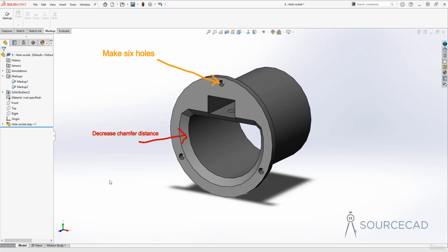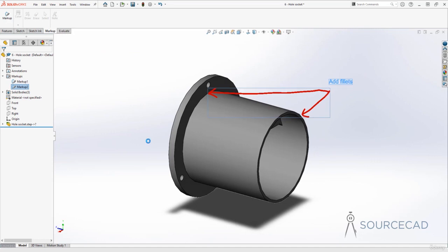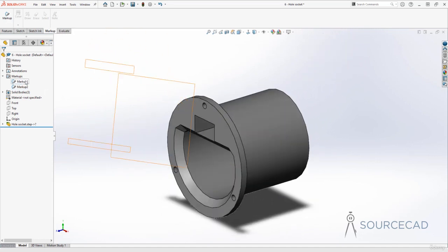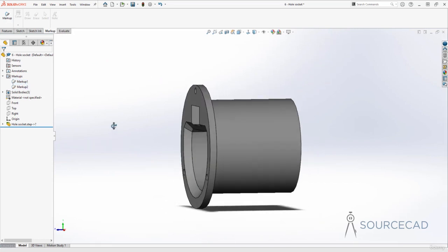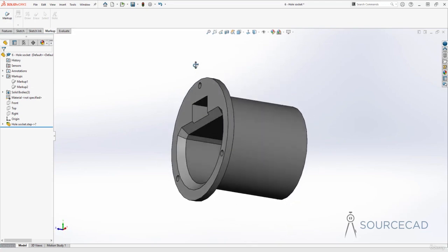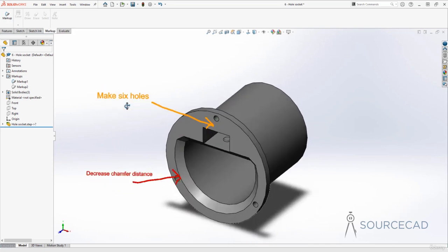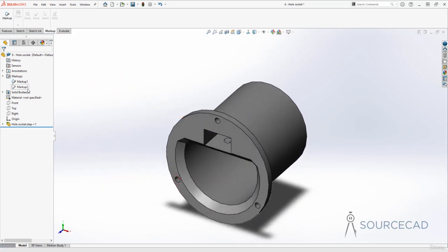Or if you just send this SolidWorks part file, well, anyone can just change to that markup view and see what's inside these markups. Now, if you want to hide these markups, you can do so very easily as well. So just go to the markup and select hide, and now the markups won't show up, kind of like this. So here we are, we don't have the markup even when you orbit your drawing. If, however, you just make it visible, markups will show up when you orbit your drawing, kind of like this.